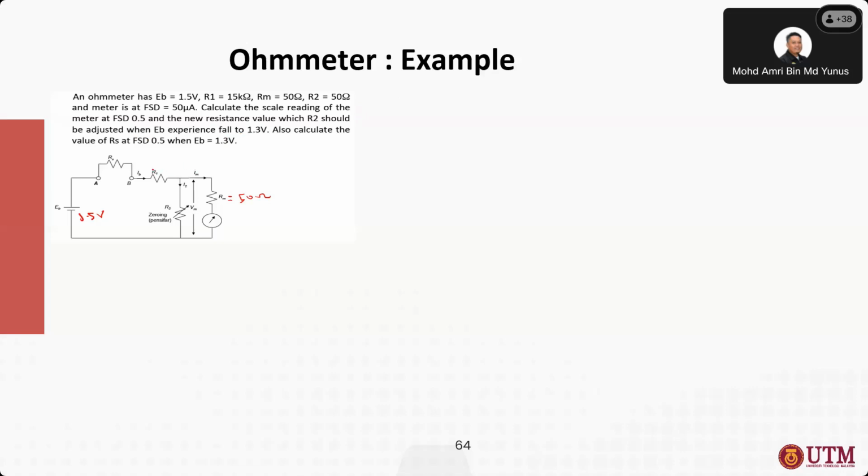At 0 ampere, and then full scale deflection IFSD is 50 microampere. That is when IFSD is full scale deflection.